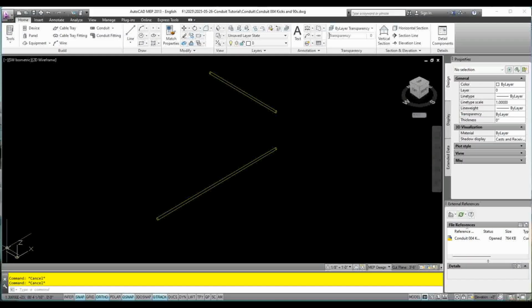Well, look at the XY plane right now. It's XY, right? Well, we want to kick this up and then 90 into this piece of pipe. To kick it up, right now we're in the XZ plane. We cannot kick on that plane. We need to rotate Y to Z, and then we can kick it, right? So, okay, let's do that.